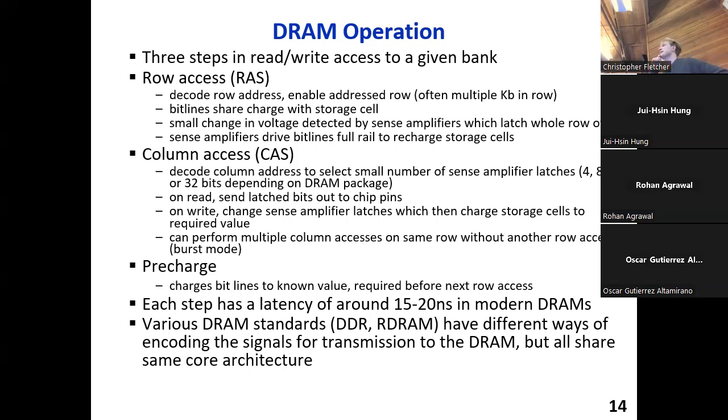So if you set it to say Vref, or let's call that 0, and you actually want to dump out a bucket which is storing a 1, you're going to have to dump out more water to bring it from a 0 to a 1 than half to 1. And so half is a midpoint where, if you set all the bit lines to that, the potential difference needed to register as a logic 1 or a logic 0 is minimized if you have no assumptions on the data patterns written there.